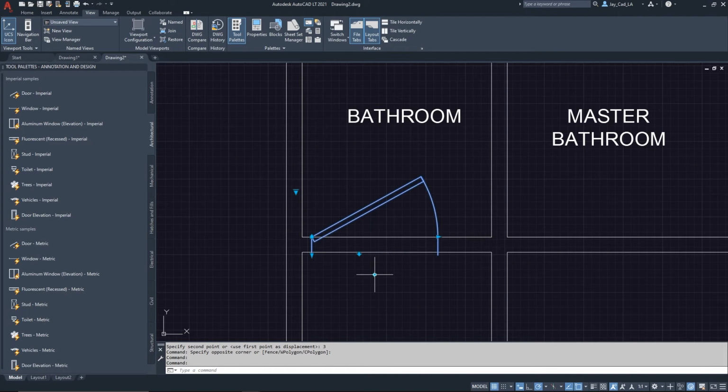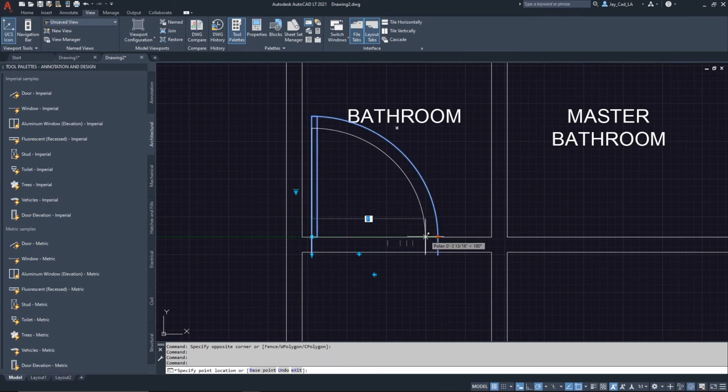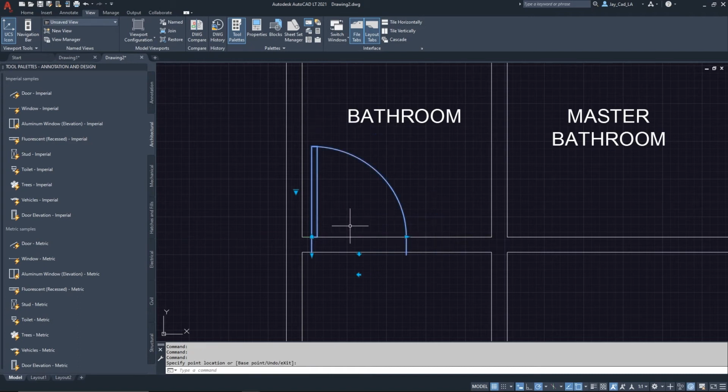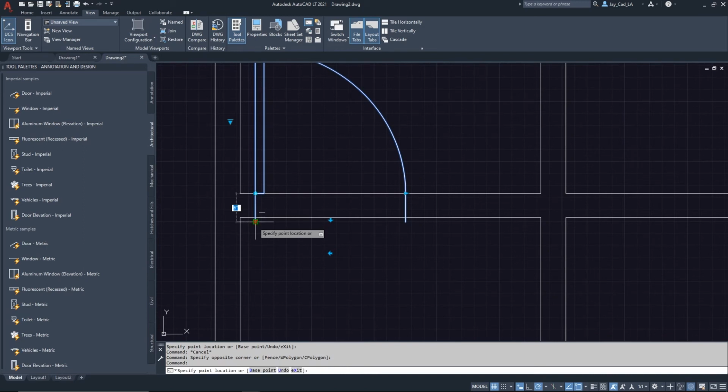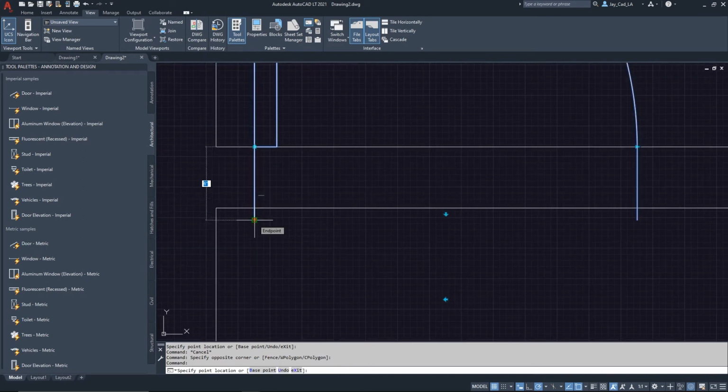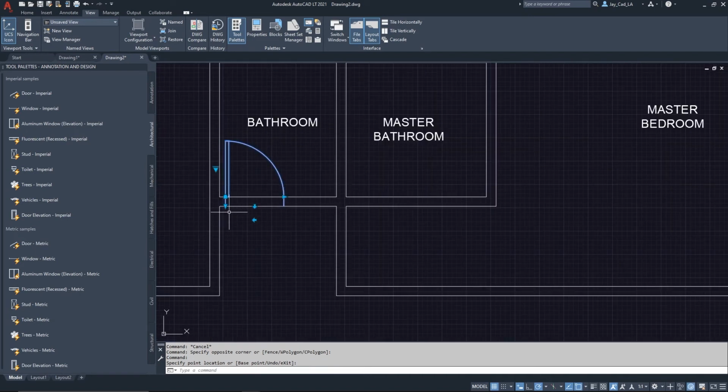So I can flip the direction of this door in and out, like the swing direction. And then from here, I can choose the open angle. And from this arrow, I can modify the width of this door. So I'm gonna choose 2 feet 6 over here. Okay, and then even here on the bottom, I can choose the wall thickness where this door sits. So I'm gonna switch it to 5 inches over here.